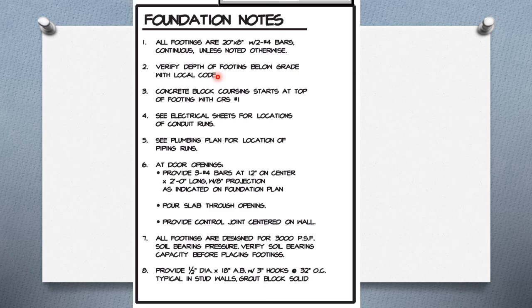In an area such as Florida, my frost line is very, very close to the surface. You're not going to get freezing to a great depth. Here in Ohio, that frost line might go down as far as 3 feet. So you have to excavate below 3 feet.